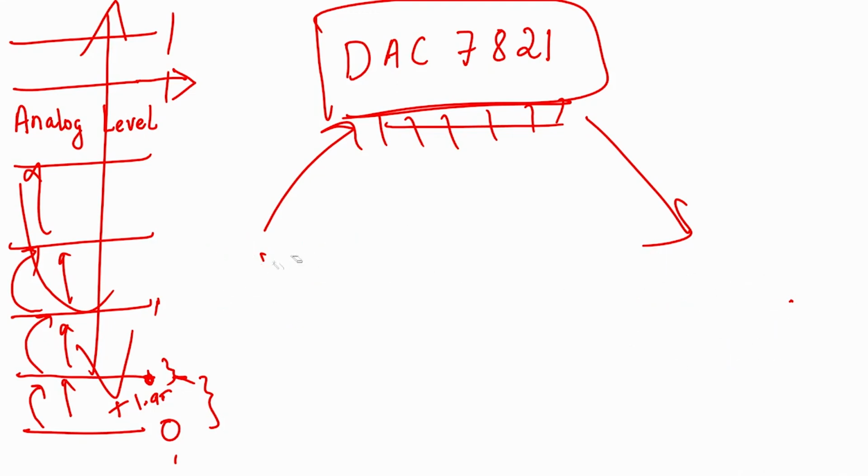Always, when you are designing or when you are looking at somebody else's design, both of which you will encounter in your professional career, you should be very careful to understand it to the extent possible, because it is not possible to go through the data sheet of every single resistor, capacitor, and IC in the circuit. You should try to understand at least the main components, the data sheet, and how it is to be used.